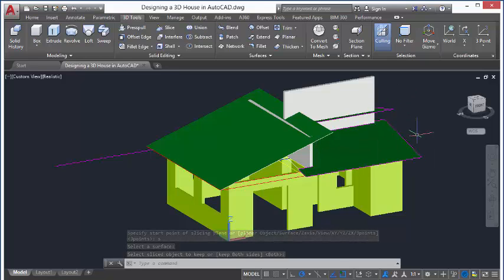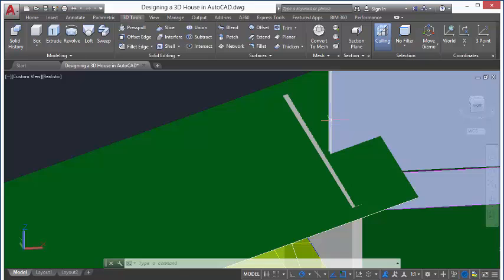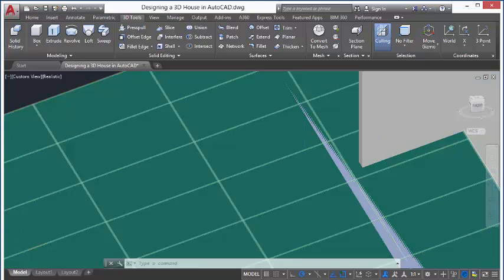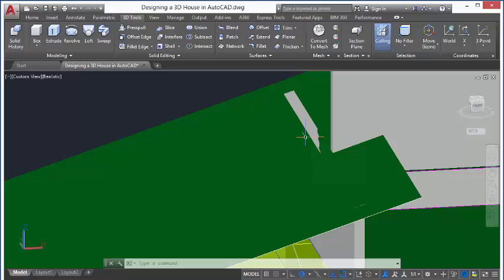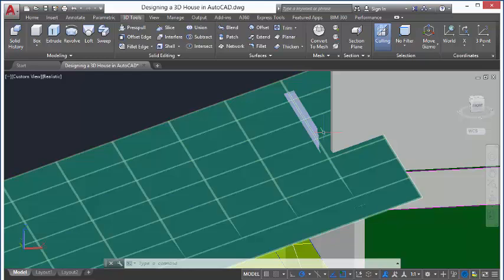So the other area that you don't select is gotten rid of, and the one that you select remains. As you can see, the slice command uses the surface of the roof to slice the wall. So the wall is showing above because it slices at 0 distance. So we need to get rid of this problem.